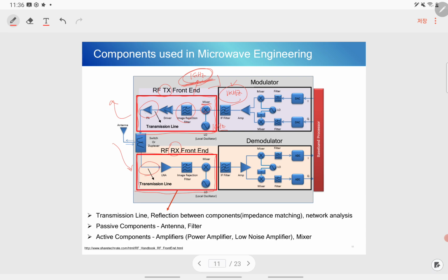We amplify the signal generated from the voice and send it out, and the receiver side gets the signal from the antenna. Basically, when the transmitter is working, this switch is connected to the TX side, and when the device works in receiver mode, the switch changes.